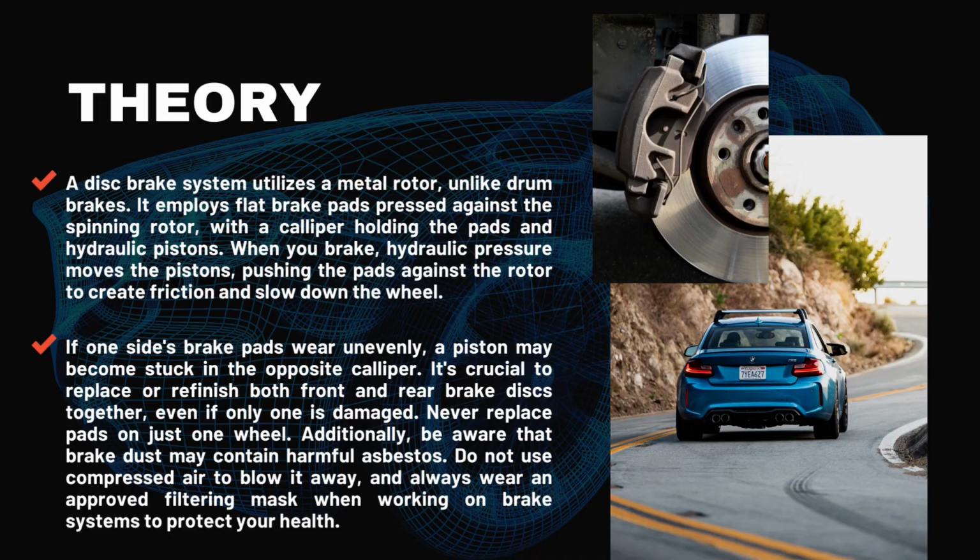To simplify the theory, a disc brake system uses a metal rotor and flat brake pads to create friction for braking. Hydraulic pressure pushes the pads against the rotor to slow down the wheel. If one side's brake pad is unevenly replaced, refinish or replace both front and rear brake discs together. Never replace pads on just one wheel. Also, brake dust can be harmful, so don't blow it away with compressed air, and wear a filtering mask when working on brakes for safety.